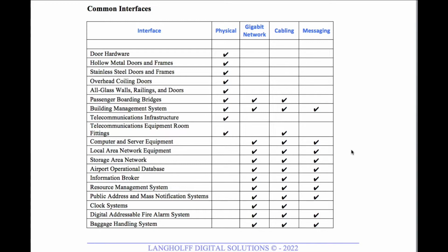So in the case of, say, a building management system, you may want your access control system to talk to the building management system such that if the building management system has some type of fault, perhaps it is monitoring some power, you want to notify the access control system that you may have lost power to some number of locks. This means that if there's a power failure, the doors would be unlocked so that if anybody's inside, they could get out.